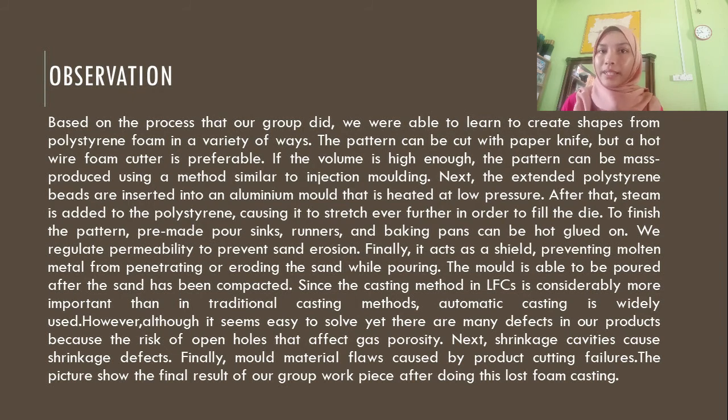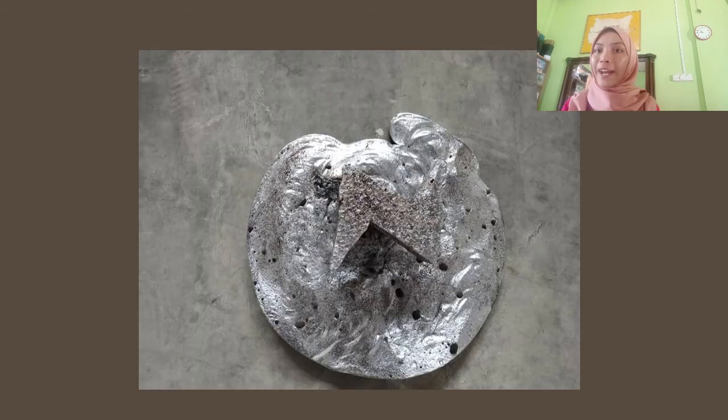The casting method in LFC is considerably more important than in traditional casting methods. Automatic casting is widely used. However, although it seems easy to solve, there are many defects in our products because of the risk of open holes that affect gas porosity, net shrinkage cavities that cause shrinkage defects, and lastly, more material flow caused by product cutting failures. Then, I will show the pictures of our group final result after doing this lost foam casting.